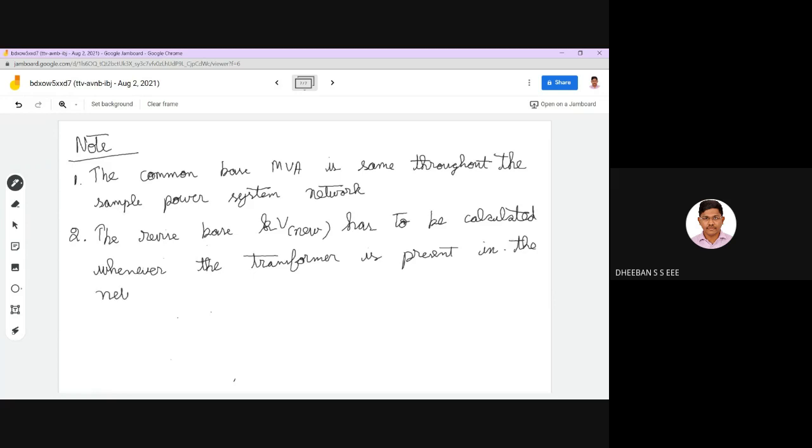In case of transformers, we will have a primary as well as a secondary. In most cases, we won't have the same voltage rating in the transformer in the power system. So you'll either have a step up transformer or a step down transformer. Based upon that, you have to adjust the voltage rating, even your impedance diagram. While solving the problem, we'll get into the idea. So how can you find this revised base value?